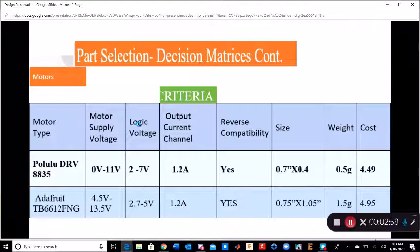It starts operating at 3.7 volts to 6 volts, so that one fits perfectly here. But if we choose the Adafruit one, it starts operating at 4.5 volts, so we have to use a boost converter here, which will result in more weight.